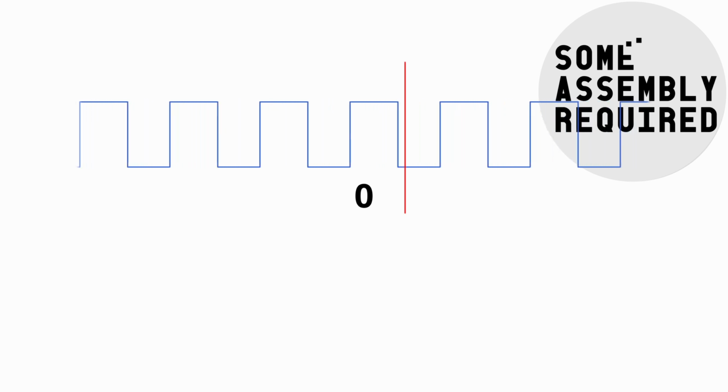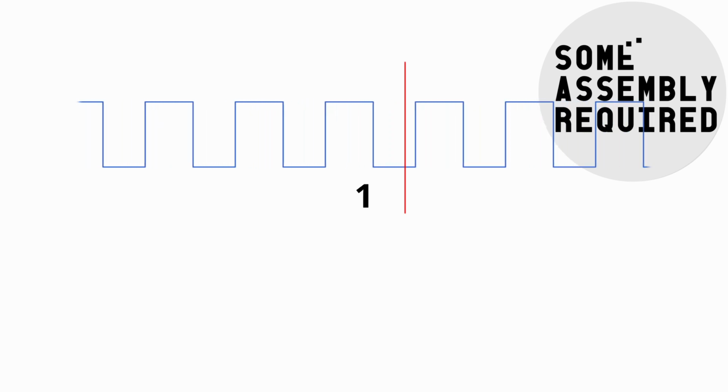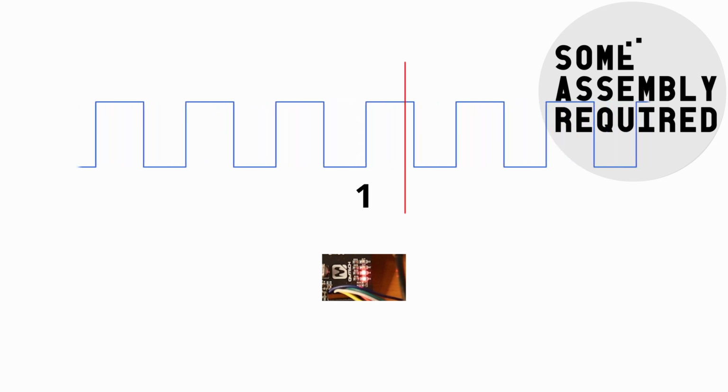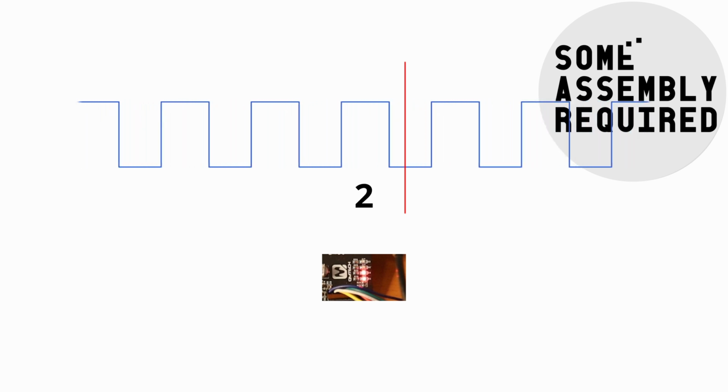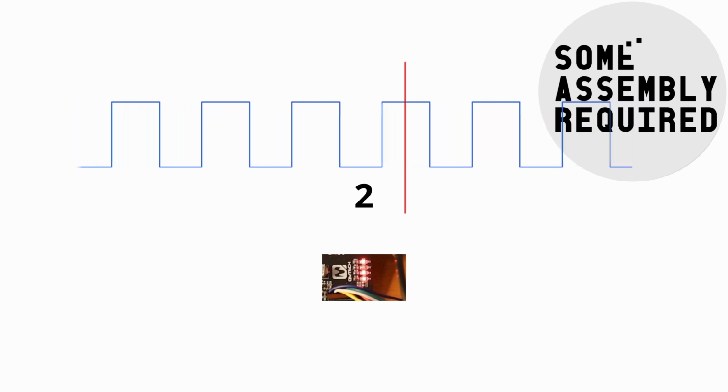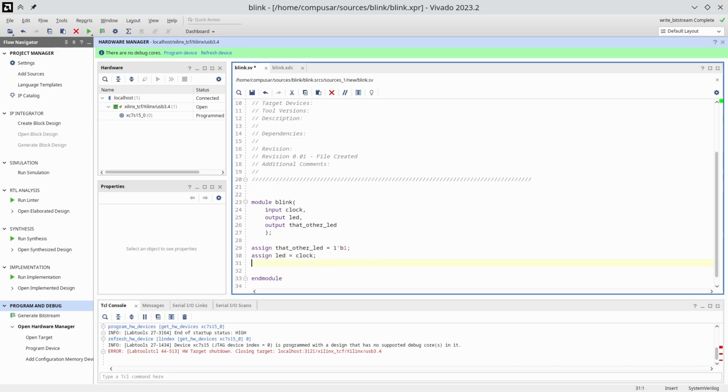These work like this. We take a counter. Every time we see a clock, we increase the timer. When it gets to our divider number, we reset the counter and change the state of the LED. The first thing we need is code that runs when the clock goes high. In SystemVerilog, this is done with the always_ff block, FF standing for flip-flop.